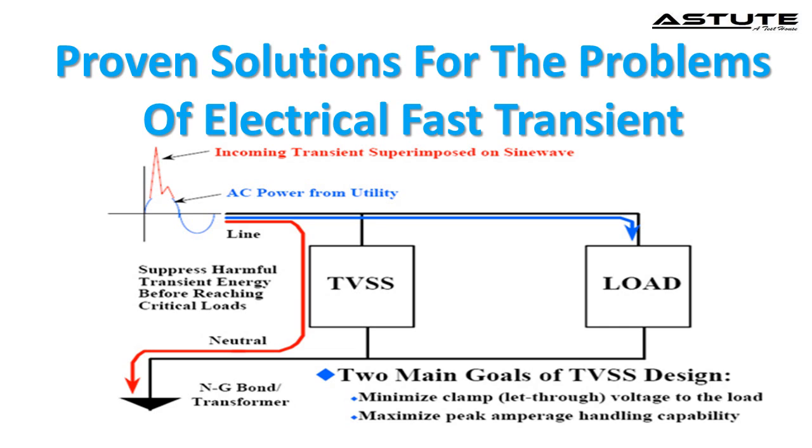Employ good soldering of wires or components. Improper or dry soldering will increase the inductance on the path. A good design should have the least inductance on the current path. Refer to Electronics Assembly Standard IPC-A-610F for more details on the soldering practices. Use MOV for EFT suppression. Also use a TVS diode.